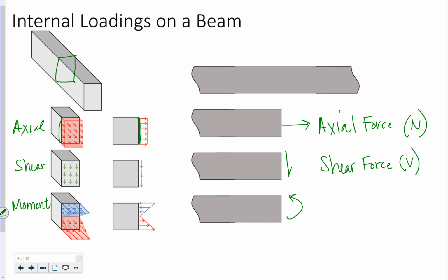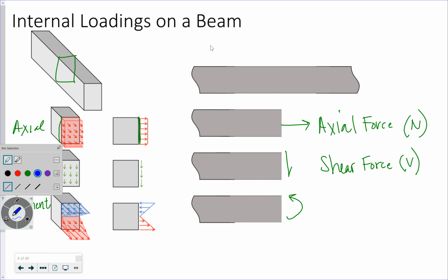In this case, it's a moment where we have tension on the bottom and compression on the top, right? If I were to take the resultant of that compressive stress and the resultant of that tensile stress, there's some distance between them. That's my force couple. I get a moment.